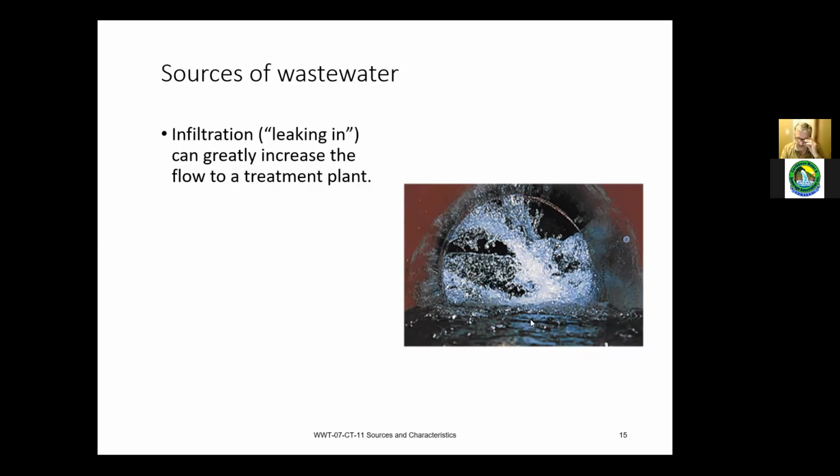A good way to test for that type of infiltration is smoke testing. You put a canister of smoke in the sewer system, and it migrates. As you can see, this line's not full, so the smoke would migrate through the spaces and work its way up. You see the smoke rising from people's roofs and houses, and it tells you they're tied in improperly. Our main goal is to educate people, so if that happens, we don't run out with bylaw to find them. It's more of an education.